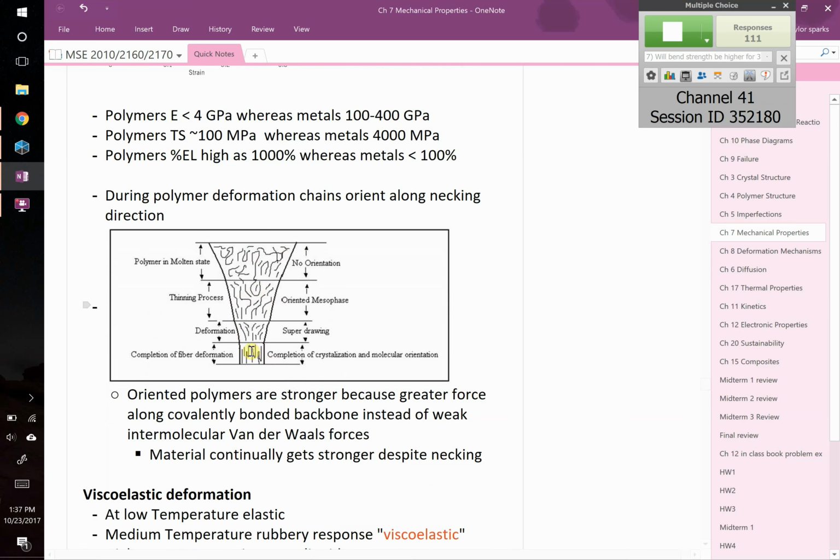Yeah? You see that behavior in other materials, not just polymers? The strain rate and the temperature. Oh yeah. Metals, for example, absolutely. It's more pronounced in polymers because they melt at a low temperature, and so the temperature needed for them to overcome their van der Waals bonding is low compared to metals. But yeah, you absolutely will see that in metals and ceramics, right? That's why a couple chapters ago we showed you the picture of the Liberty ship, which in cold water became very brittle when that metal was expected to be pretty ductile. It underwent a ductile-brittle transition, just like you saw there.